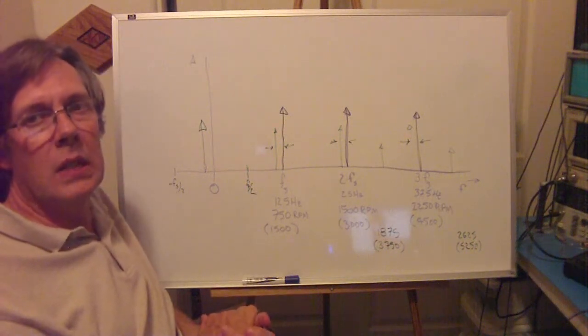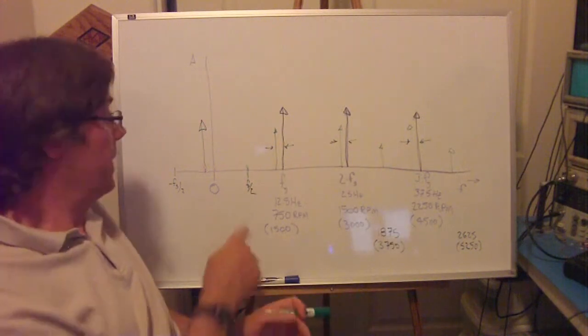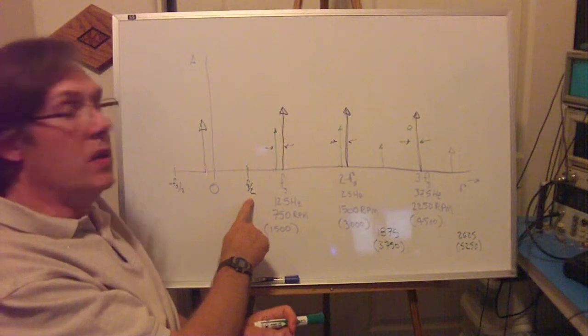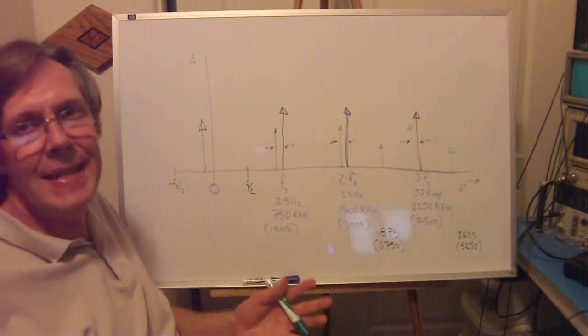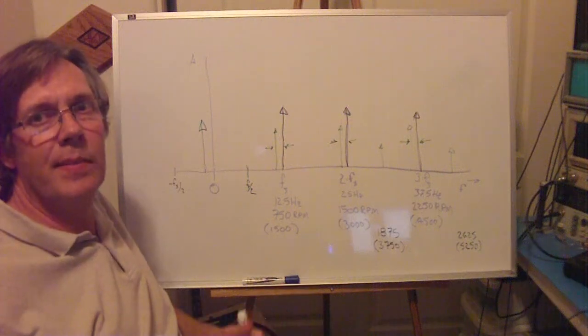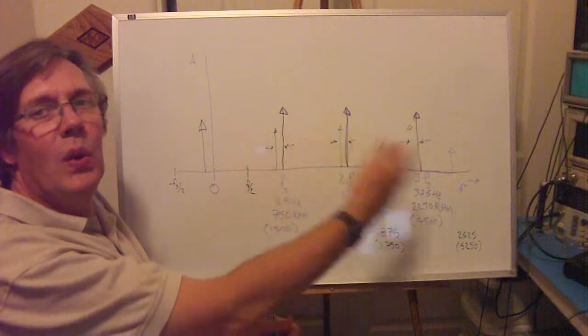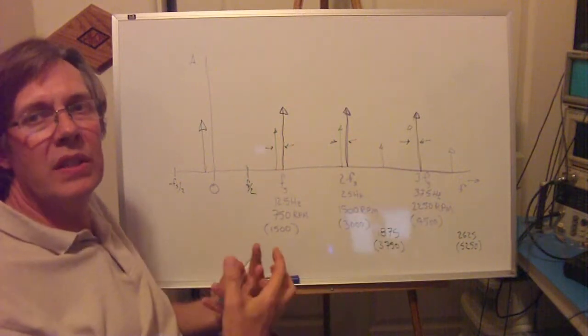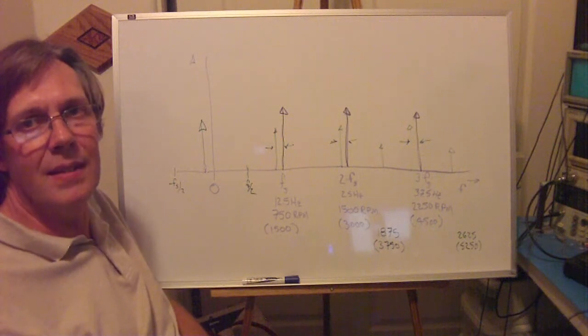The way you do this in a signal processing system is you filter out everything above half of the sampling rate. And then you know there's no energy out there that is possible to come in and alias. So that's why it's called an anti-alias filter: you're trying to knock out everything from f sub s over 2 and above, so that when you look at the signal, you know it was in here. That's basically it.